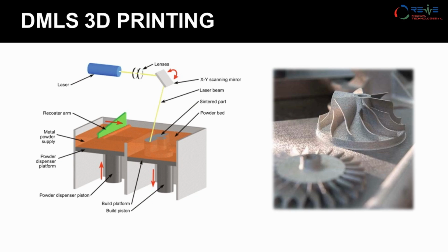But there are a lot of issues in this process as well. Here, PAPRs come into place. Without PAPRs, they are not recommended to be used because the dust is so toxic that breathing it in is very dangerous. There have been a lot of cases when people used this technology and had critical issues, metal poisoning and stuff like that. So PAPRs are a must when using these devices, and a lot of companies use those in this technology specifically.